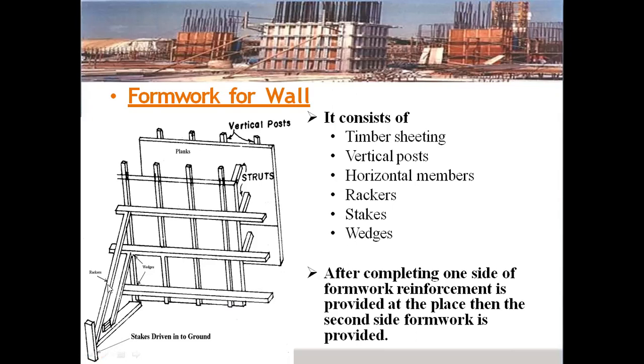So when the fluid concrete has been poured into this mold, this load has been applied to the vertical post, then transferred to the horizontal members, and these horizontal members can be placed in position by the rackers. If the load is heavy, these rackers are helpful, with the support of the stakes which are driven into the ground.